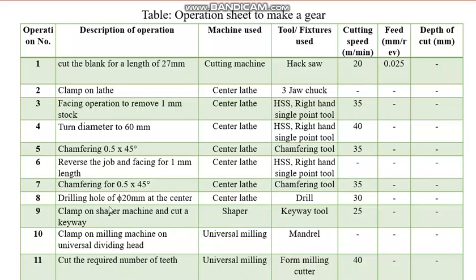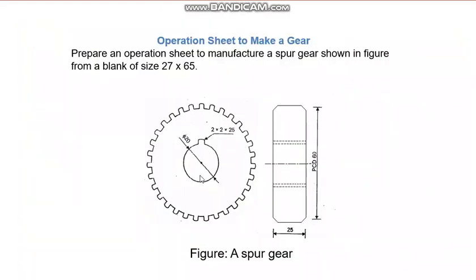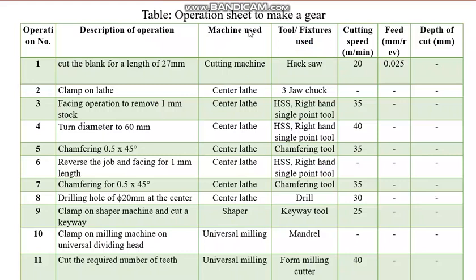And you have to drill a hole, a center hole. See here, initially as a blank it won't have one, it will be a solid cylindrical rod. How will you drill the hole? That is also possible on the lathe. You start with a center drill and then drill. You can fix this on the tailstock, and you can drill the hole.